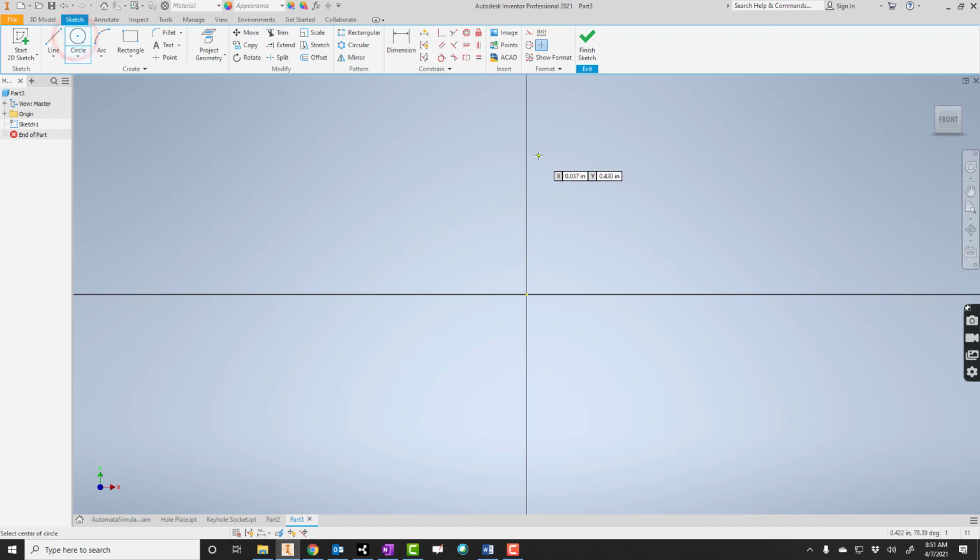First thing I'll do is I'll draw just a circle. Now this circle is going to end up being the diameter of the spring, so you could define that however you wanted to. For now, we're just going to put something together here. Below that, somewhere, I'm just going to put a line. I could use the origin, and in the future I would recommend that, but just for the demo, I'll just draw a line straight out.